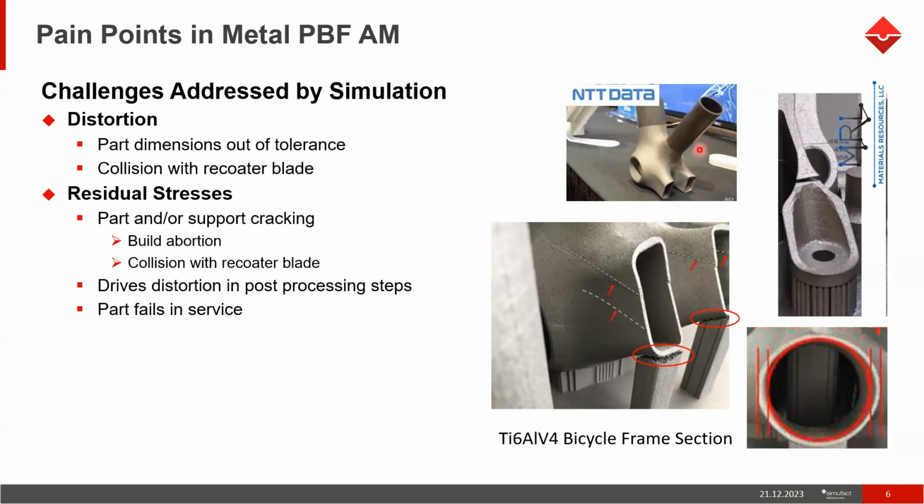So these support structures also are a part of the manufacturing process. They are also built along with the part. Later they are removed by some processes. You can use some tools to remove these, and we cut it from the base plate. Such operations are done to remove these support structures from the parent part, whatever part we are manufacturing.